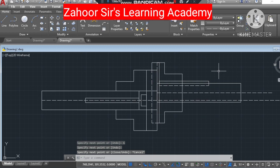So this is how we have shown the keys, and most of the things have been done. You have to draw the continuous sign here in the shaft ends, because these shaft ends need to be shown with the continuity sign.